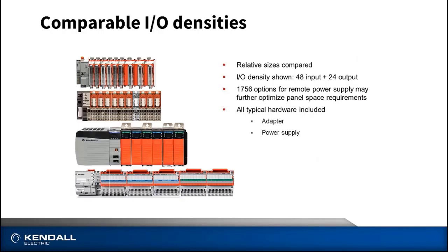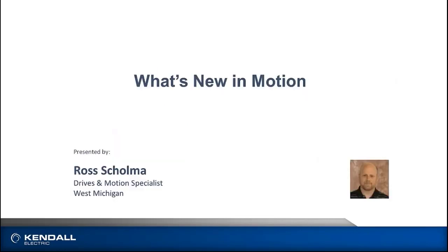I guess the last point I would make, down on the Flex 5000, remember that both the input and output modules, safety modules, are 16 channels. So in this case, we have 5 modules there. The first 3 are 16-point input modules to give us the 48 inputs. And then the last 2 are actually 16-point outputs. So we actually have 32 safety rated outputs on the Flex 5000 configuration that you see there. And with that, that concludes my portion.